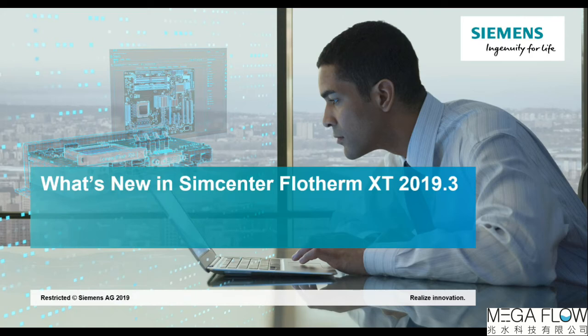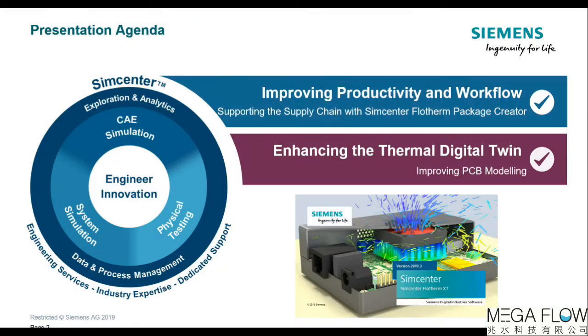Thank you, Byron. I would now like to move on to the features introduced in Simcenter Flotherm XT 2019.3, released in December alongside Simcenter Flotherm. Two major enhancements have been made. Simcenter Flotherm Package Creator supports a supply chain of electronic components to improve the workflow when including devices in your model. Secondly, further improvements have been made to the modelling of PCBs to enhance the accuracy of the thermal digital twin.